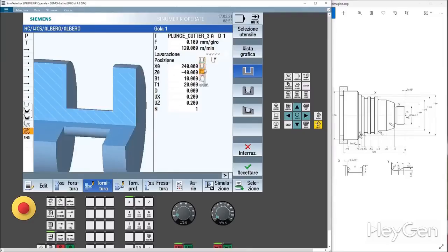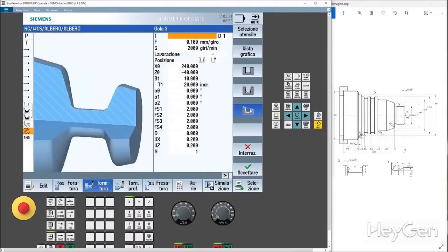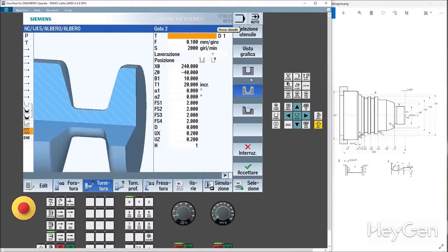Do you see how the groove is? It's on the outside, it's frontal, it's internal, it's pulled in. What is the 0 point of the groove? Reference point, right angle. What type of groove do we have? Do we have a square groove? Do we have a groove on an inclined plane? Or we have, as it interests us, a groove with radii at the bottom and chamfers.